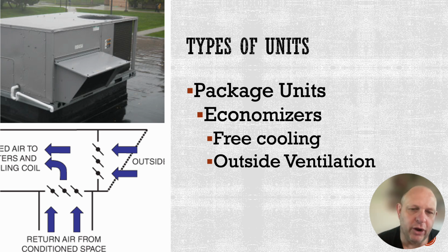Now, with our economizer, we usually have two stages of cooling. One stage will be the compressor, and then the other stage will be the economizer. The first stage is the economizer when the air temperature is well below what our conditions are and abilities to cool that place down. We'll open up that damper, allow outdoor air to come into it, and then if we are still requiring additional cooling in that area because of the heat load, we can kick the compressor on and provide mechanical refrigeration for our unit to start to work.